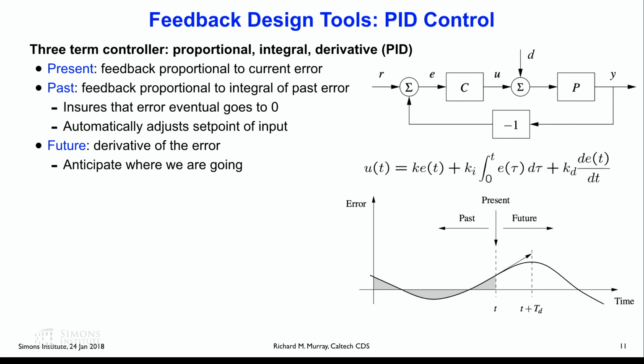So whenever you put integral feedback in, what you're sort of guaranteed if you design it right is that the error will go exactly to 0. This is what your car uses to go to exactly 55 miles an hour. You go up a small hill, it'll push a little bit. You go up a bigger hill, it'll integrate up and it'll push more. And it will get it up to the limits of the amount of input you can apply. Obviously, if I go up a hill that's so steep that my engine cannot apply enough torque to go up it, something's not going to work anymore and I'm going to have to slow down.